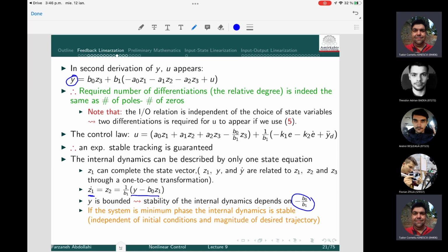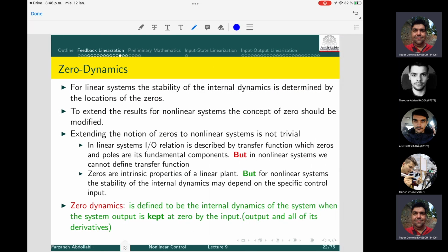Due to Bode, a good frequency range is when the phase is minimal, when the controller does not bring too much phase to destabilize the system. This is the idea. And minimum phase systems have this property. So they are very good for control. That's what it means. Minimum phase systems are very, very good and very useful for control, and much easier to control than non-minimum phase systems.